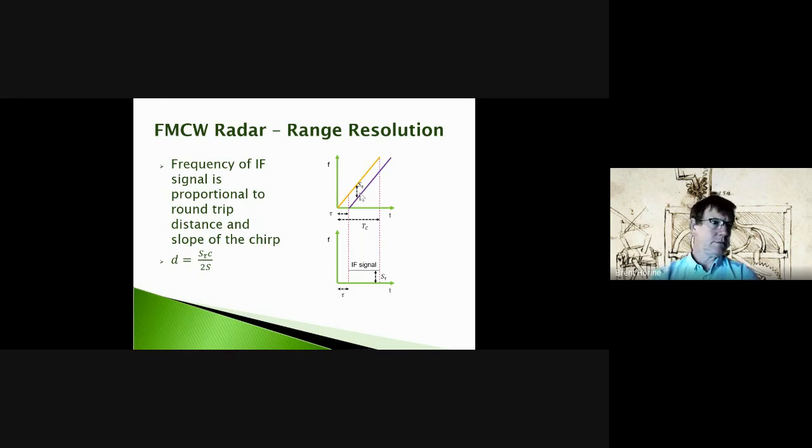That's really details in your applied electromagnetics courses, so we won't go into that type of thing. But yeah, it's going to reflect particularly off of metal objects and come back. Some of that energy comes back to the receiver, and we receive that, but there's a delay that we represent as tau here. And it turns out that the reflected signal, of course, has that same chirp behavior.